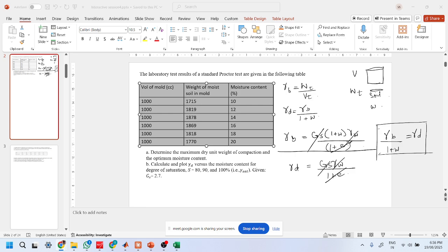I get the notification that somebody has asked a question, otherwise I would not know. So you're asking whether quicksand is a type of soil. As I said, it is not. It may seem like a plain thing, but it is actually a condition that happens to occur in a particular situation. If the soil has a particular gradation, it has to be sandy and saturated.